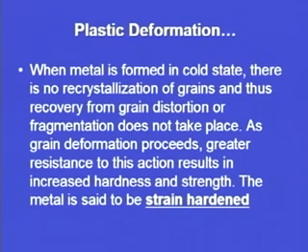So, whenever a metal is formed in a cold state, there is no recrystallization of grains, and thus no recovery from grain distortion or fragmentation. Already we have seen that when metal deformation takes place, grain fragmentation is one of the common phenomena. Grain distortion or grain fragmentation is not relieved in cold working.